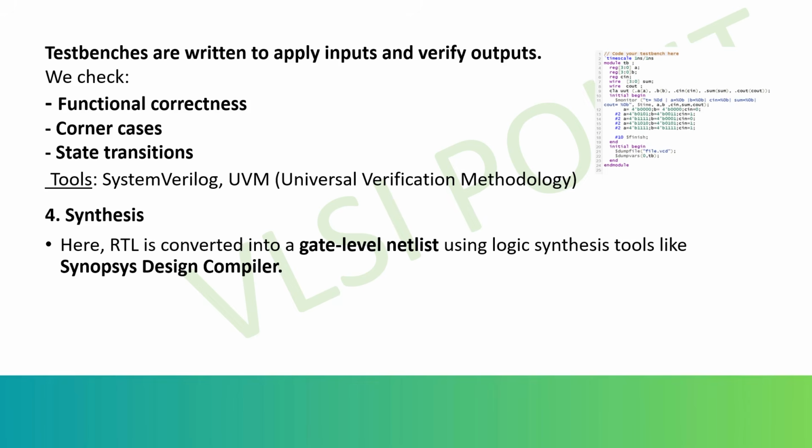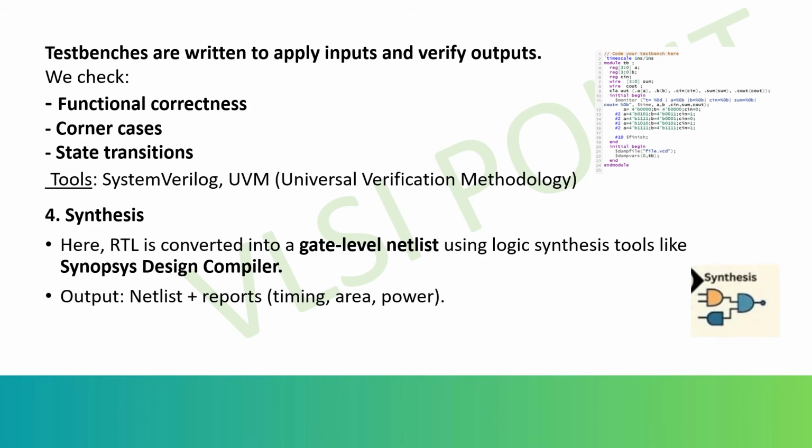The tool optimizes the design for area, speed, and power. And the output will be gate level netlist, timing report, and area and power report. You can use Synopsys Design Compiler, Cadence Genus, and this step translates your HDL code into real hardware logic.